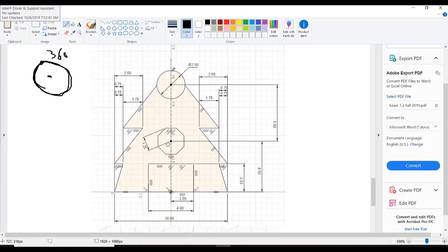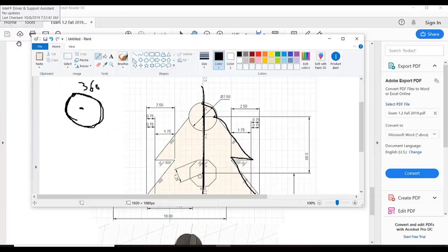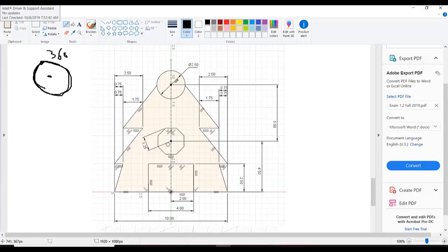in Fusion 360, to use the revolve command, basically we need the half sketch of the section which we are going to revolve. So basically we are going to make this half sketch in Fusion 360, and then we are going to revolve it around this axis. We can also do that by making this full sketch and then just revolving the half profile of the sketch. We can do it either of two ways.